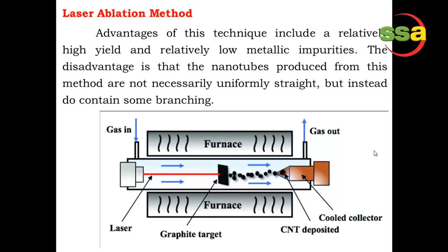That means first of all the material which is to be converted into nanotube is powderized or split into very tiny particles, and these tiny particles next deposit on the tip of the target, which is called the seed or nucleus, which is then removed from the tip, and the size of the carbon nanotube which is formed can be controlled.